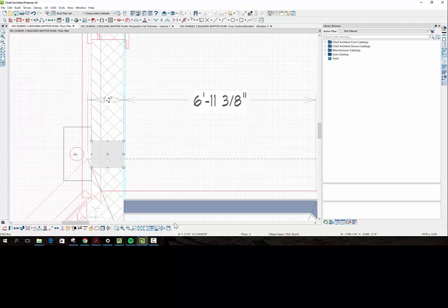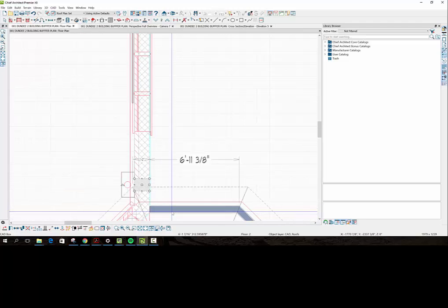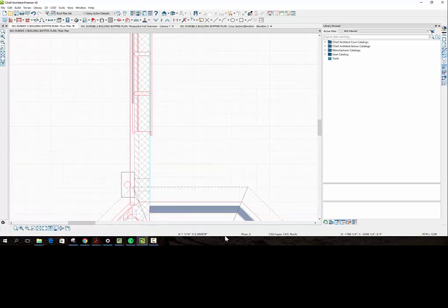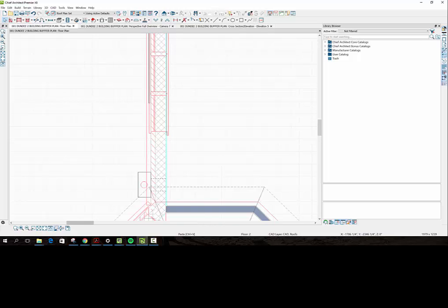And you can see that that's in the center of the circle. It's our hole in the roof. And so we locate it there. Now we've got this thing coming down here. But then the water gets trapped into this corner. We don't want it trapped in this corner. So we're going to need to build a little cricket from there to the wall edge.